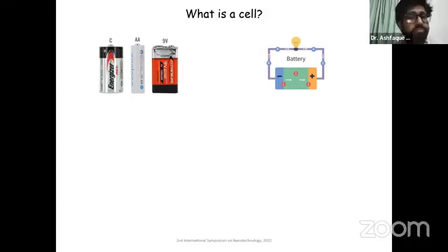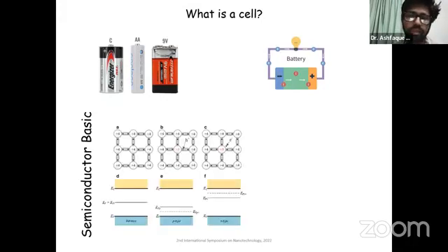For a solar cell, that pretty much reiterates, and in a solar cell, that same process of separating two different charges to two different terminals is carried out using very simple semiconductor junctions. From the basics of semiconductors, we know that intrinsic semiconductors, that means the semiconductors which are not doped, have the Fermi level exactly in the middle of the band structure.